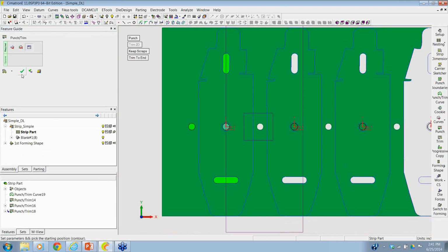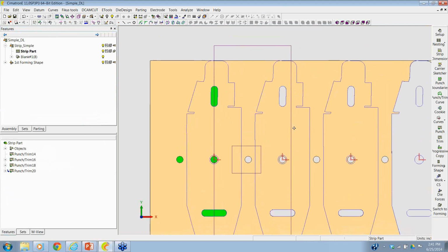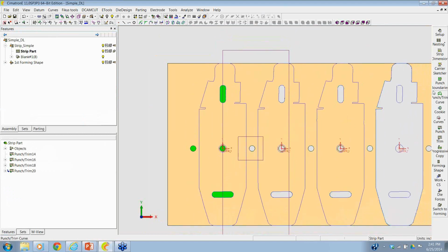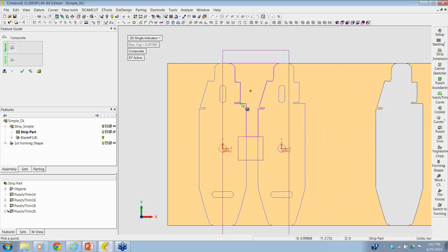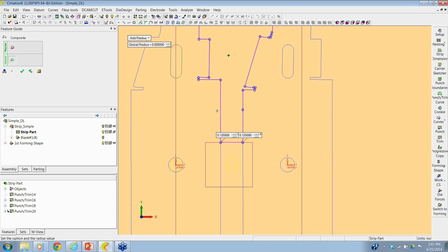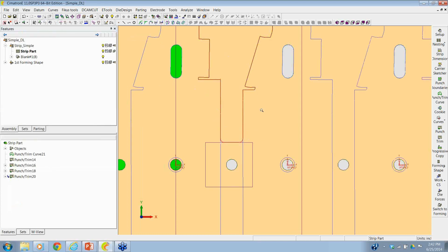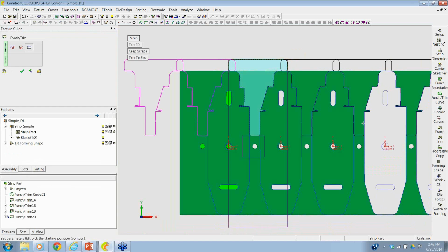That I put on a simple punch pin. Probably want to get it out of the Danly catalog or something like it. Now I've got 2 big wire EDM punches. Because real world, I'm going to do something about this. I wouldn't want to put all that on a single punch. So just so you know, I haven't completely lost my mind here. And then I'd also, as we go, we can add chamfers, add radiuses. We also can use cookies, which are very nice for extending a notch into the side of material so that I don't have a shear on shear condition with 2 punches.